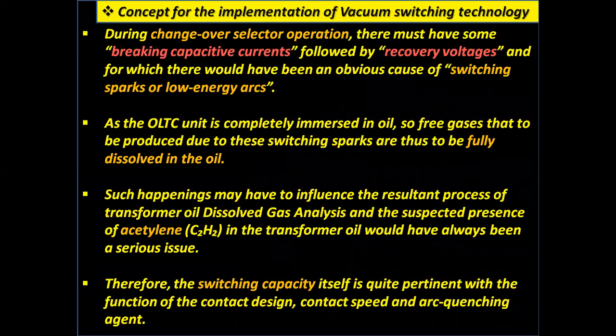Concept for the implementation of vacuum switching technology. During changeover selector operation, there must be some breaking capacitive currents followed by recovery voltages, and for which there would have been an obvious cause of switching sparks and low energy arc.